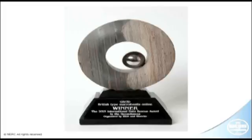And of course, as soon as I got it back, I passed it across to our team to scan it. And of course, the problems we had, as you might guess, it has a silver ball in the middle. That was very difficult to scan using the laser scanner. And of course, the bits between the ball and the circle, in fact, the inside of the circle, were very difficult to capture using the laser scanner. So this is one we did try photogrammetry instead and have got much better results.